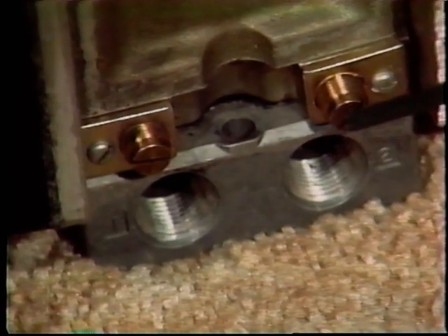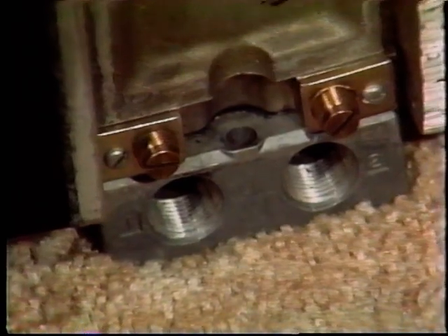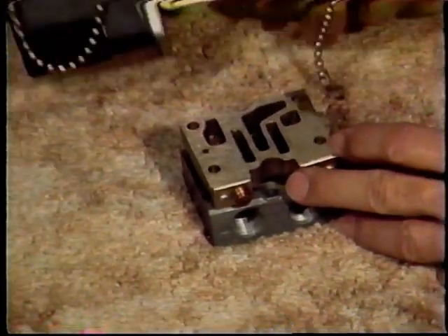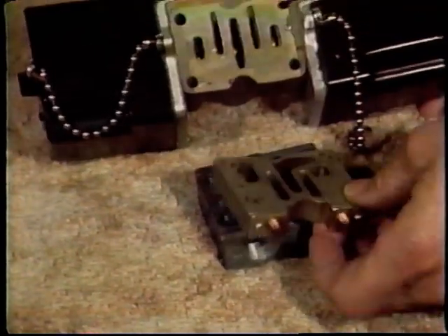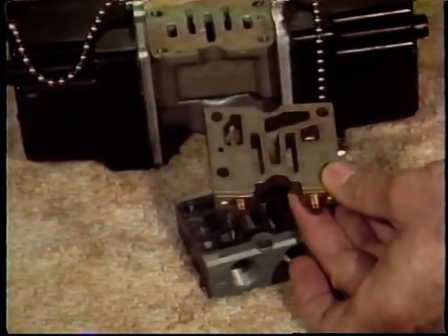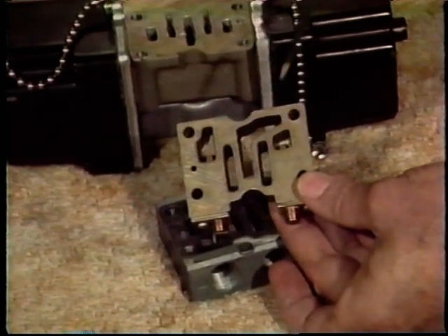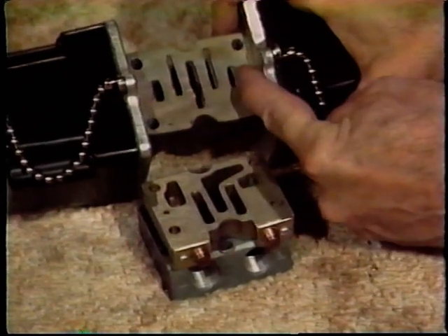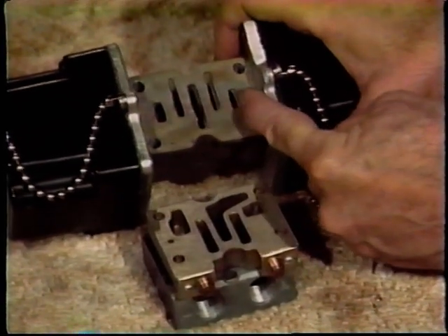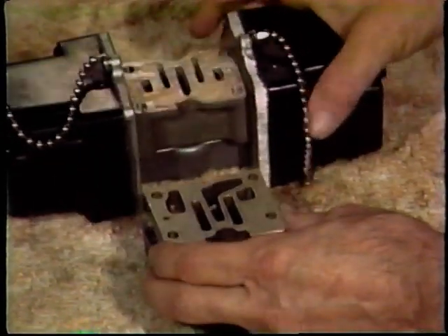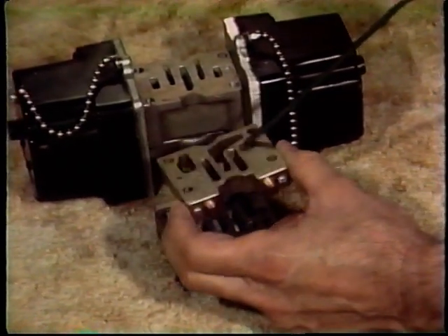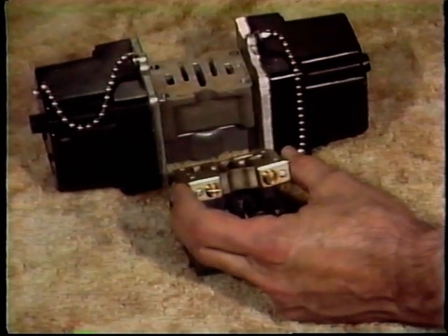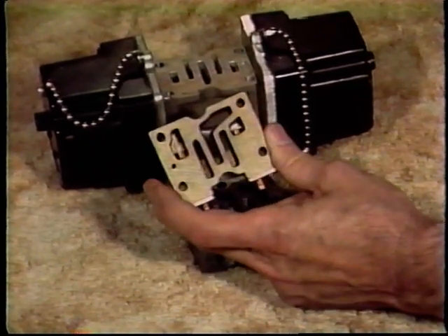It is often called a sandwich flow control because it's designed to be inserted between a directional control valve and its subplate. This particular unit has two needle valves here and here. The passages which direct airflow to the directional control valve are cast into the valve, as you can see here. And since the unit utilizes two needle valves, it's often a convenient unit to use when a circuit requires a cylinder to have different rates of extension and retraction.